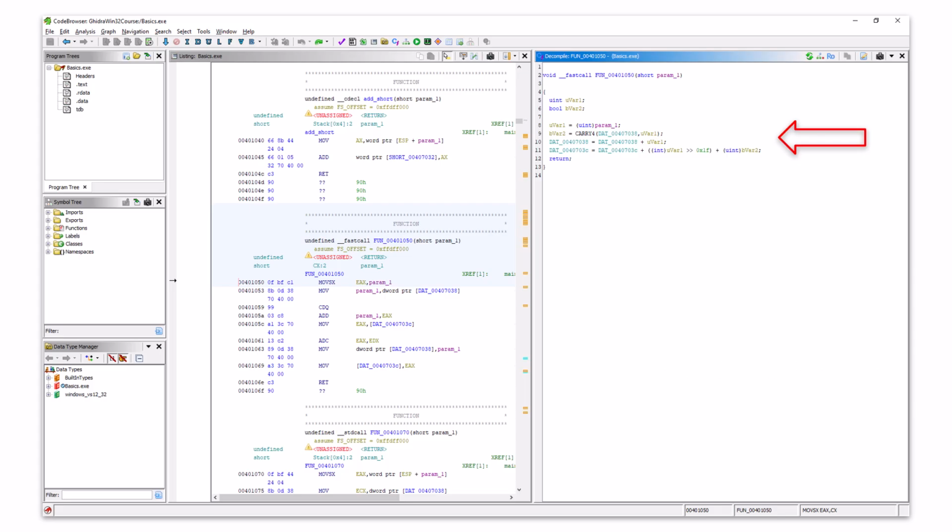Now, let's take a look at the compiled code once more to figure out why a simple addition was transformed into so many instructions. The reason for this is that the program is compiled to be executed on a 32-bit CPU, while the variable is a 64-bit value, which does not fit into a CPU register for direct computation.